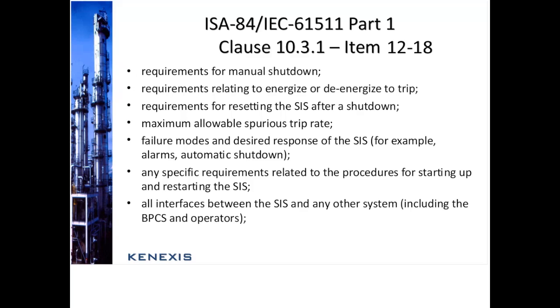Failure modes and desired response of the SIS, alarms, automatic shutdowns. So if you have a failure in the SIS, failure of a transmitter, automatic shutdowns, failure modes, these are the types of things that need to be considered. Any special requirements related to the procedures for starting up and restarting the SIS.